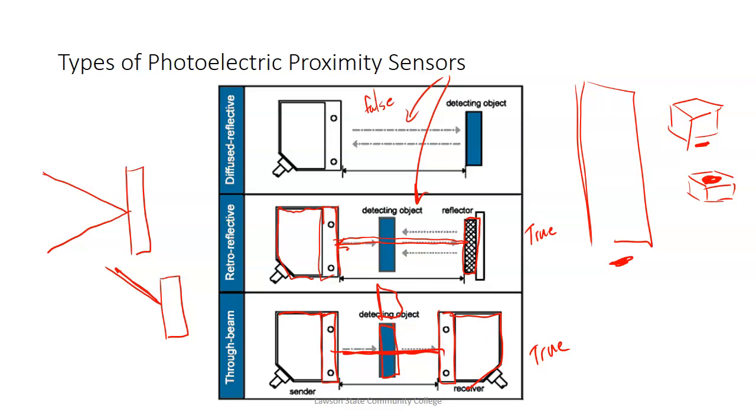So what we did is we put in a through the beam detector, and these things must have been, good gracious, 100 feet apart. Originally, we put it pretty close to the ground, but the rats and everything would set it off. So we moved it up to probably a foot off the ground, and those things worked great. Then they put a real small gauge wire down the chain link fence that you couldn't even see, and if somebody cut it to get in there, it would break the wire. So those are the two things we added. But the through the beam units were at least 100 feet apart.